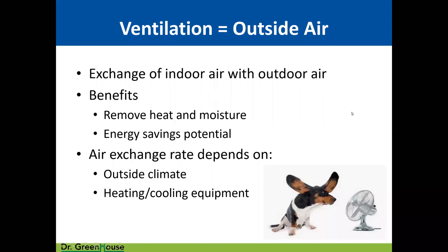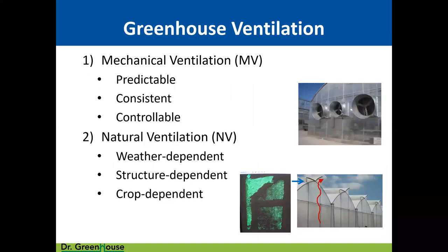Okay, so ventilation, basically it equals outside air. Ventilation does not mean air movement, it means outside air. And again, we're exchanging indoor air with outdoor air, we're removing heat and moisture, and there's energy savings potential. How much we ventilate and whether or not we ventilate depends on a couple of things. One, what is the outside climate relative to the inside climate? And what other heating and cooling equipment do we have available?